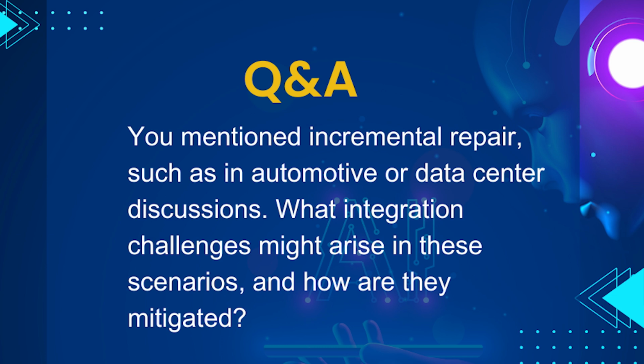Oh, yeah, this question is quite sharp. If incremental repair for on-system or in-field maintenance is required, two things have to be met. First, sufficient OTP capacity, which means the OTP needs to reserve space for in-field or on-system repair.